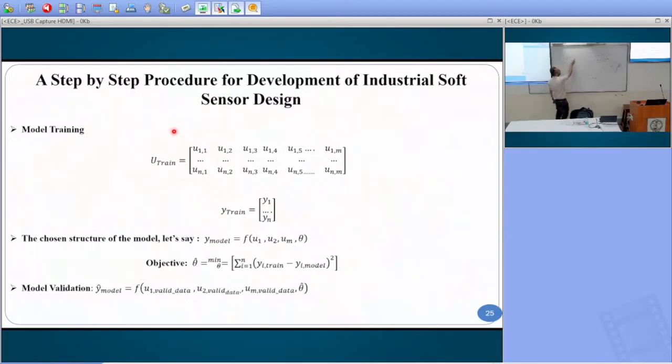So I want to make sure that I minimize this error as close to 0 as possible. If this error is close to 0, then this can be my model which can predict my true measurement. Okay. So I want to reduce the error between the yk, which is the plant data, and y predictions. Y predictions are nothing but the model a into un, so y plant minus y hat is the error. This error I want to minimize for a batch of data.